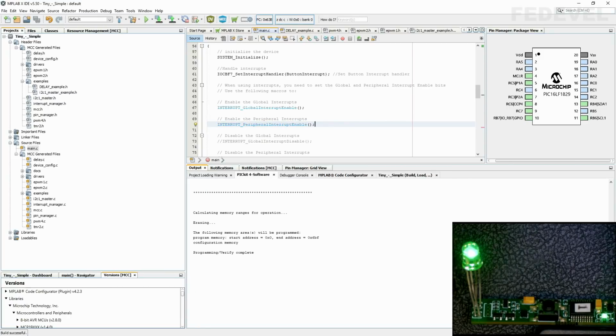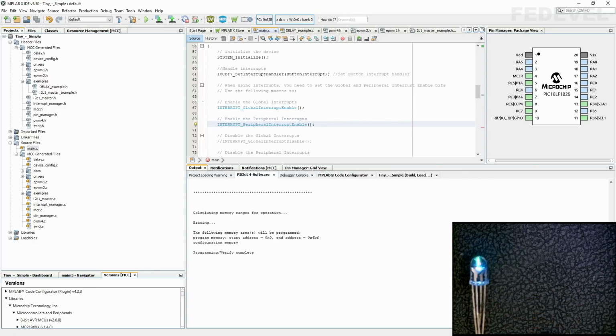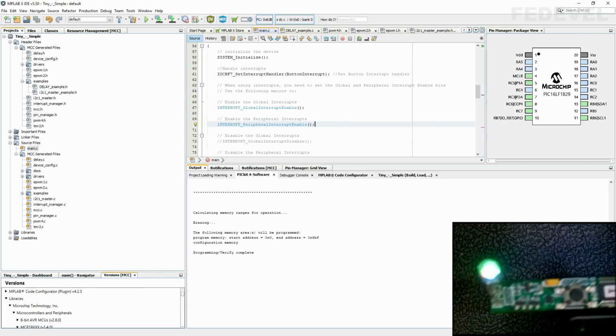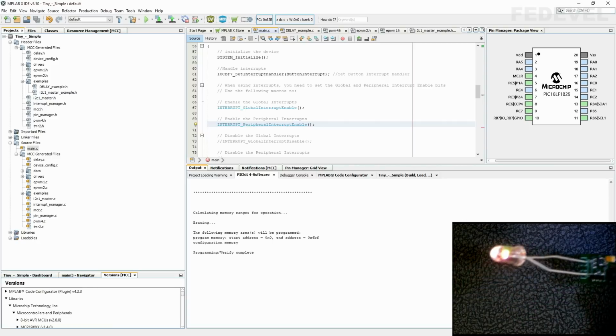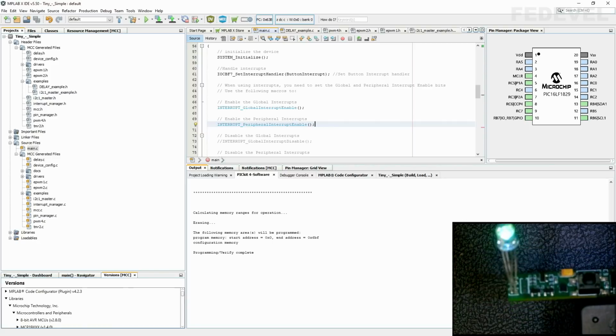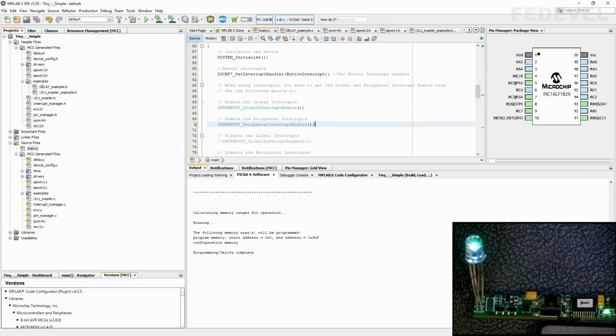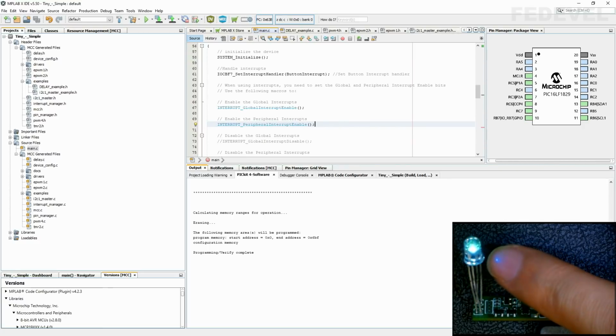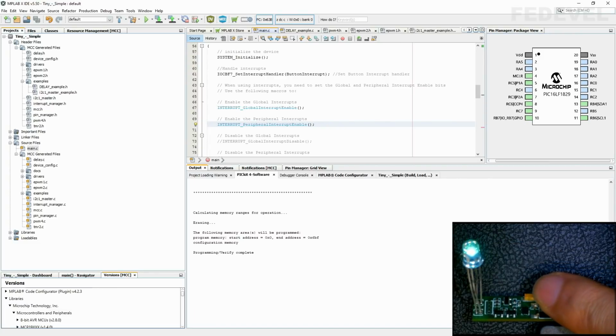Okay, green LED, it means the microcontroller can communicate with the accelerometer. Our original software is still working. You can see this is the blue LED, this is the green one, and the red one. And the new feature that we just created is that when we press this button, the color of the LED should be white, full brightness for 3 seconds. So let's try it. Yes, the interrupt is working perfectly fine.